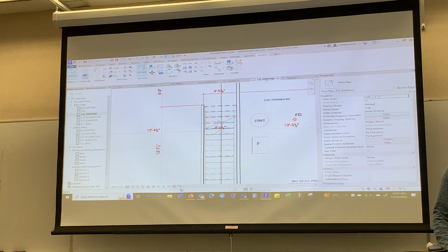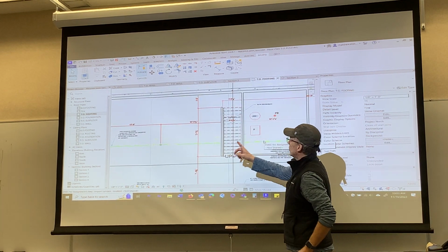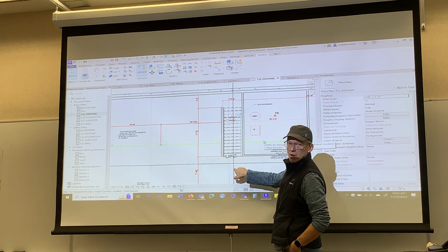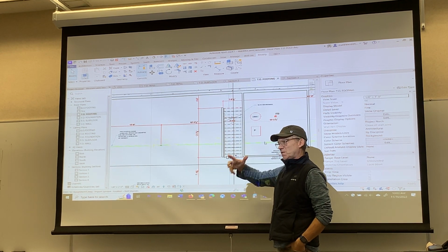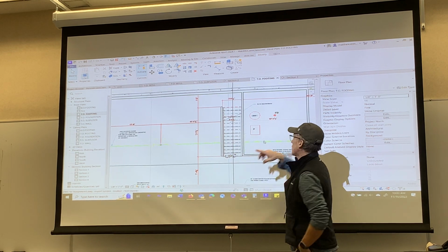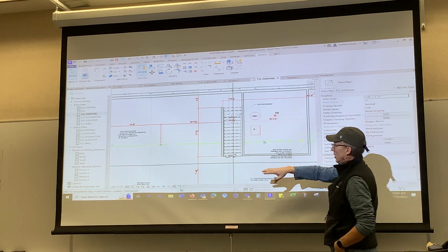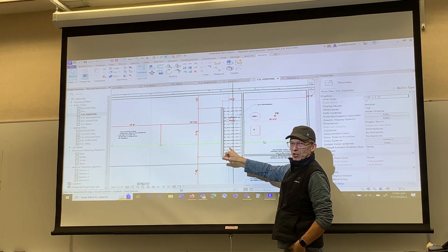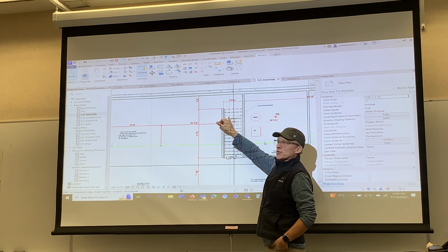Especially because the stringer's 2 inches high here. So when you first put them in, start way out here somewhere and drag them up until... I'm saying feel it, but there's a calculator working in the background, because I've told it I want to start at top of footing plus 3 inches to subfloor. It'll sense that when you're pulling it, because it's doing the math, and it'll want to stop, so stop short.